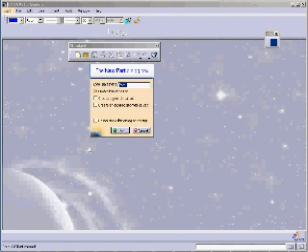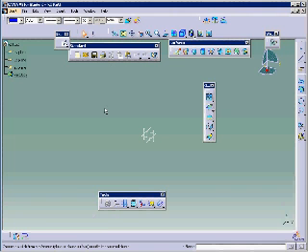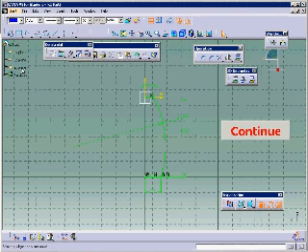The New Part dialog box is displayed. Enter C11.1 in the Enter Part Name selection area, and choose OK. The base surface of this model will be created by extruding the sketch drawn on the ZX plane. Choose the Sketch button, and select ZX plane from the specification tree. Draw the sketch of the base surface, as shown in figure, and exit the Sketcher workbench.